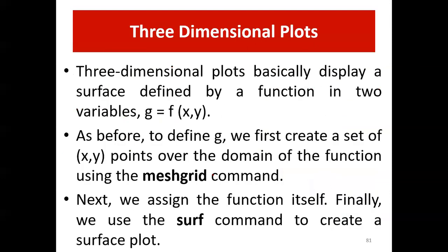Then the three-dimensional plot. How can we generate this three-dimensional plot? In two-dimensional we use only x and y, but in three-dimensional we are going to add one more variable. Before that we want to define it, and for three-dimensional the command is meshgrid. With the help of this meshgrid, we are going to create the surface plot with the help of the surface command.